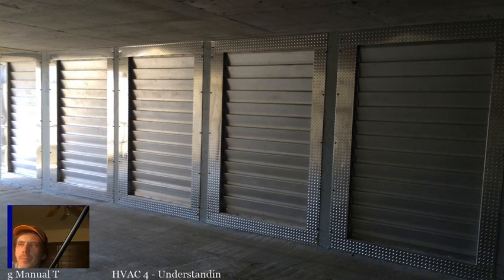Understand what the components are that are used to sense your flame coming on. So if you have a natural draft appliance with a pilot, you're usually going to prove flame if it's got a standing pilot. A standing pilot means the pilot is lit all the time. Any piece of equipment with a standing pilot is usually going to prove flame via a thermocouple.